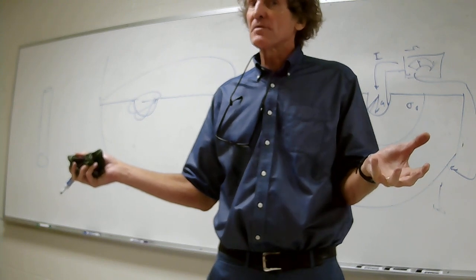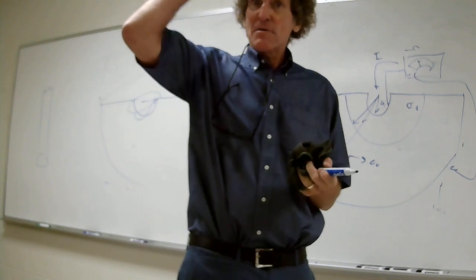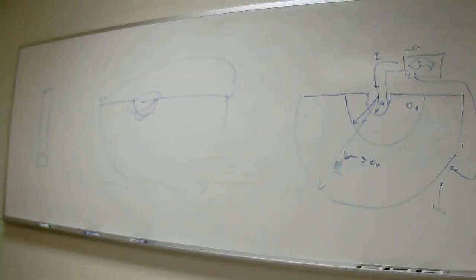So think about this just with me for a second. Suppose you ever do the balloon thing? Rub a balloon, put it on a wall? Well, the time constant, I better not do the whole thing. If you want to get the time constant decay of that charge, which is like the RC time constant for a circuit, you can approximate that balloon's radius, and then approximate the discharge point at infinity and get the resistance between that spherical thing and infinity. That's the R. Then we can get the capacitance.